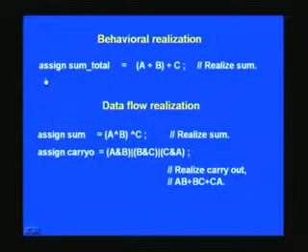And you will notice that in a single line we can realize a full adder. Another beauty of this is that it is irrespective of the bit precision. Suppose you want 16-bit precision for A and B, you can still use the very same statement. The only thing is you will have to declare A and B to be of that precision at the top of the program, which we will be covering later on.